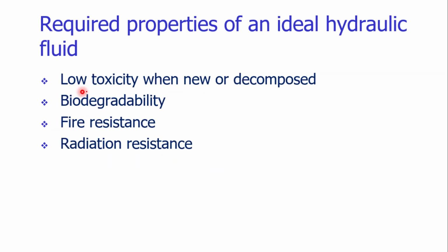The hydraulic fluid should be low toxic. We are using the hydraulic systems in presence of the human beings. The fluid will be handled by the human beings. So it should not harm the health of the human beings. It should be less toxic. It can be easily decomposed. If it is biodegradable, that would be the best hydraulic fluid. It should have the resistance capability to the fire, and it should have even the radiation resistance as well.